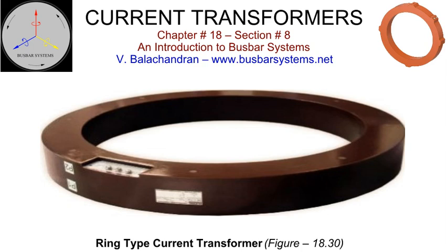Current transformers installed in the tap-off bus may have to be designed for the rated voltage if the available air clearance is not adequate to meet the basic insulation level. A conducting aluminium foil, integrally cast along the inner diameter of the current transformer, and acting as an equipotential surface, is connected to the tap-off conductor to eliminate partial discharge.